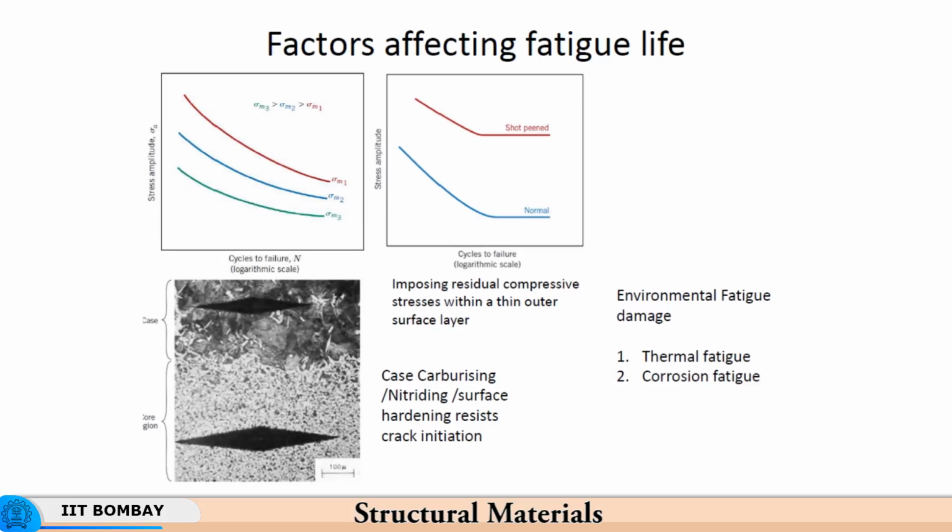When the shot has done its job of increasing the surface area and the load is released, because the shot will impact, the surface area increases due to plastic deformation. When the shot moves apart, the surface gets unloaded. Now, when the surface gets unloaded, the material locally tends to come back to its original position, but the indentation by the shot impinging on the surface has increased the surface area. The increased surface area cannot be pushed back to its original value.